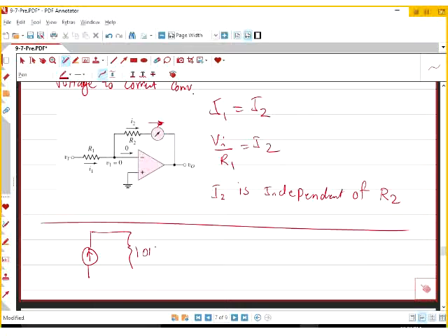You could connect it to 100K, 10K, 2K, 1K. It doesn't matter. It does not depend on the load. It depends on what is internal. The current is always constant, right? Okay. Now, this circuit is kind of like this. If you fix VI and fix R1, the current I2 is always constant. If this R2 is a load, it really doesn't matter, because this current passing through has nothing to do with the load. Agree? So this could be a current source.